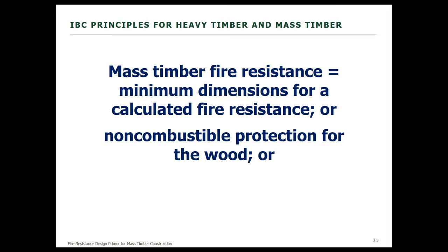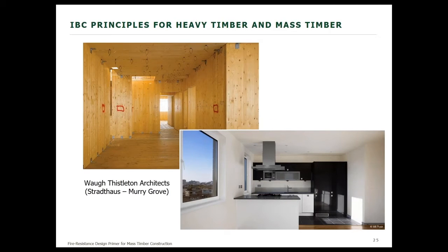Or you can accomplish the total fire resistance by adding fire resistance to the outside of the wood member in the form of layers of gypsum or some other non-combustible covering. Or you can do both. You can take the required fire resistance of the wood member itself, and then add the fire resistance of the protective layer.